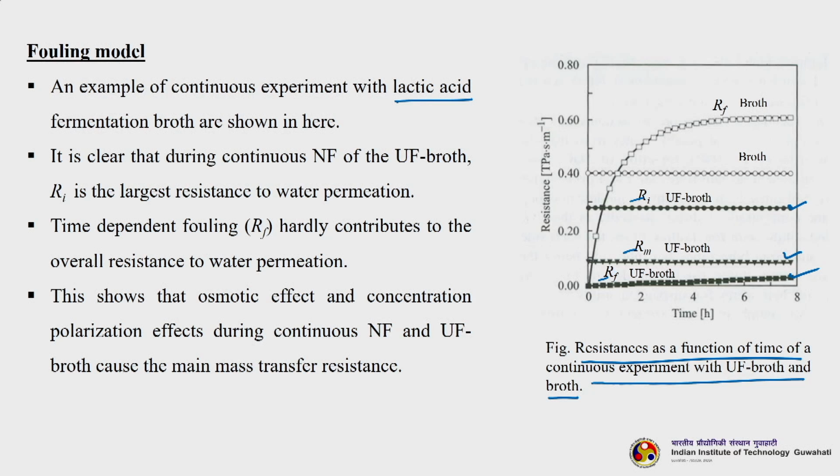So, it is clear that during the nanofiltration of the ultrafiltered broth, Ri is the largest resistance, by value you can see. Okay. So, time dependent fouling Rf hardly contributes to the overall resistance of the water permeation. So, Rf is almost negligible, so you can almost neglect the Rf. Okay. Now, this shows that osmotic effect and concentration polarization effects during continuous NF of UF broth cause the main mass transfer resistance. Okay.